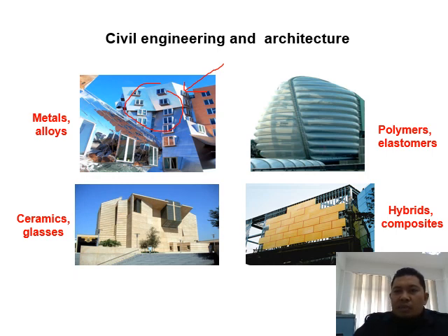Okay, as for polymers over here, sometimes you can use polycarbonate, sometimes you can use polyester. But if you make a structure and leave it outside, it will be affected by the environment. The sun is the very common enemy of polymers, because it easily oxidizes the polymers and makes them degrade, become brittle, become discolored, and so on.